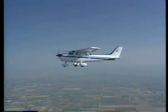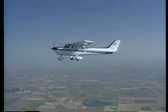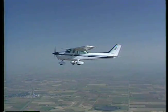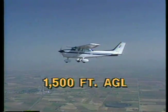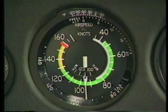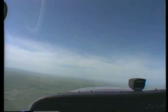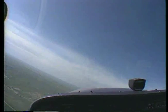Begin the maneuver with the airplane stabilized in straight and level flight at an altitude that will allow you to complete the maneuver no lower than 1,500 feet above ground level. Your airspeed should be at the manufacturer's recommended speed, or, if none is given, at or below maneuvering speed. Roll into a 45-degree bank turn with coordinated aileron and rudder pressure. This bank should be smoothly established at a moderate rate without rushing.